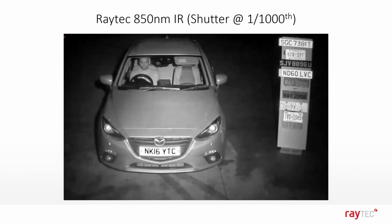Next we have is an example where we have put the shutter speed to 1/1000 with standard 850 nanometers. So yes, the car is stationary right now, but even if that was going 70 miles per hour, we're going to get pretty much the same image quality as that. So 850 nanometers is probably industry standard wavelength for infrared. 90+% of the cameras are using that kind of wavelength because it's perfect for CCTV and it's not very visible to the human eye when you look directly at it.